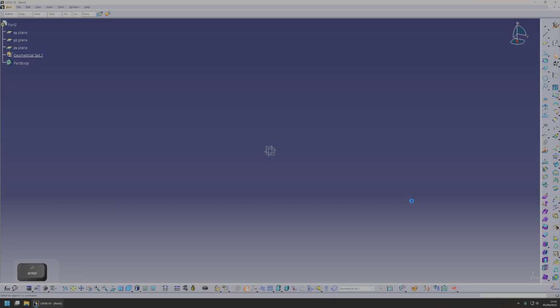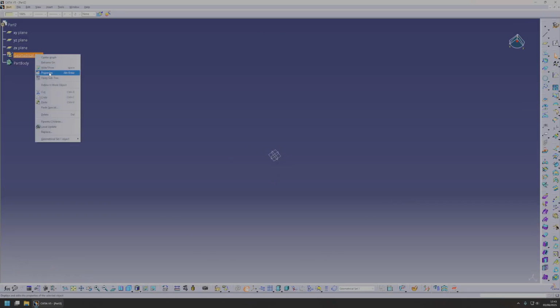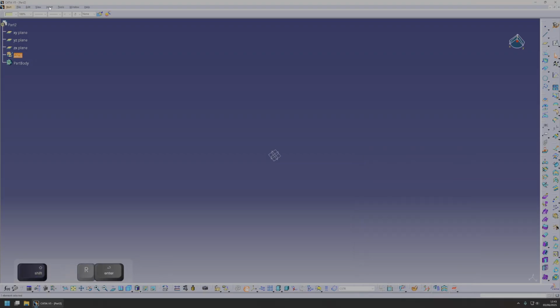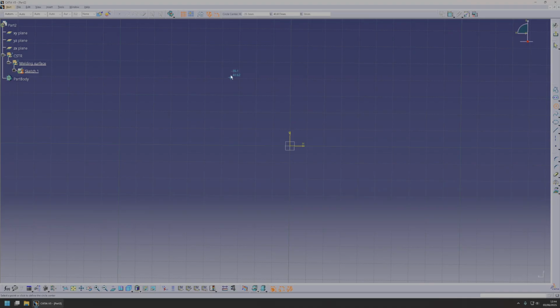Create a new part, don't worry about the name yet. Of course, we define our tree, which is the first thing you should be doing anyway. So here under the construction tree, we will create a new geoset called...